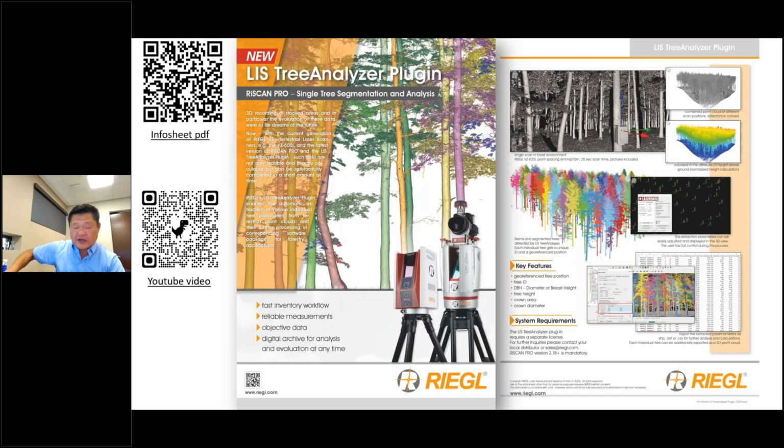And then you go ahead and copy that into another space, and you open up the parameter and increase it, and it'll find bigger trees, and you copy that over to another space. Or if you want to find smaller trees, put a smaller diameter parameter in there and define smaller. So it's a very dynamic tool. It's not just, hey, I can only define this type of size trees at this height. So it's really user defined.